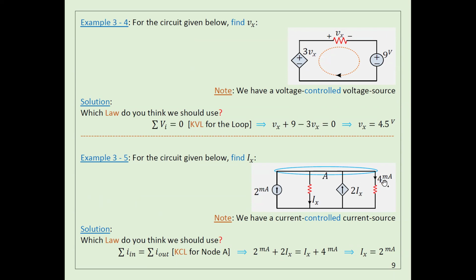And then I have a current here of 4 milliampere. What I need to know here is this current. This is a very direct, very easy application of Kirchhoff current law. This is one node, this is input, this is another input, so 2 inputs and 2 outputs. That's what I did. The inputs, this one and this one, equal the 2 outputs here. You have only one unknown, so I can calculate it.